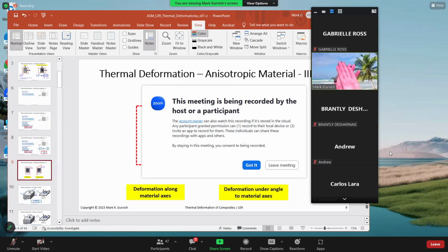But for plus minus, and this is a very common case, of course, those shear components between layers are usually the major troublemaker, and we will discuss interlaminar damage in a follow-up lecture when we go to strength analysis and damage tolerance analysis. But at least, even qualitatively, you can hopefully visualize why it happens.